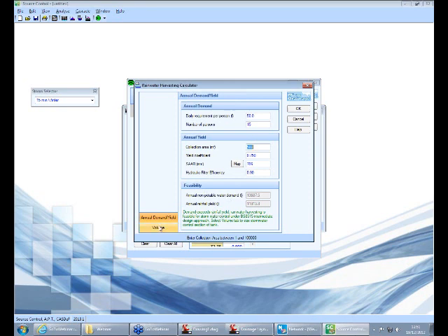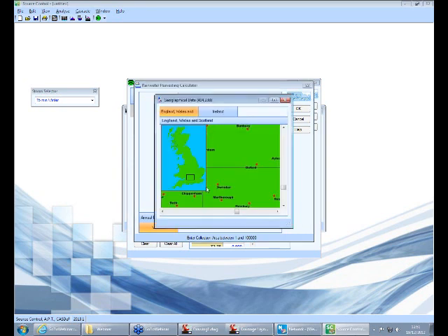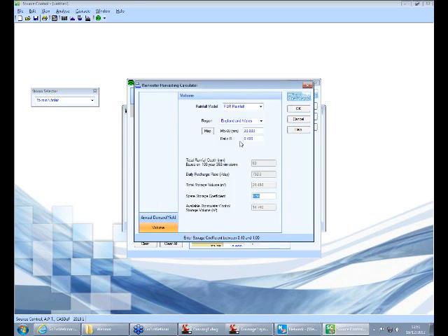In this scenario, we can move over to the volume tab. In here, we've got rainfall at the top. So again, we've picked the location where we're working, and it uses various calculations based on the British Standard to calculate what size tank would be required, and so that's coming in just under 30 meters cubed. That then has a spare storage coefficient applied to it.